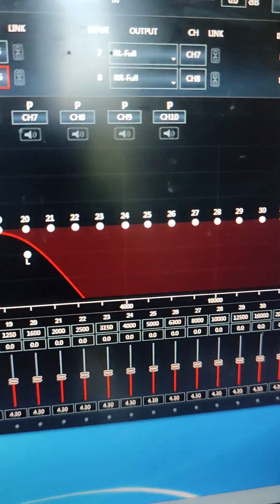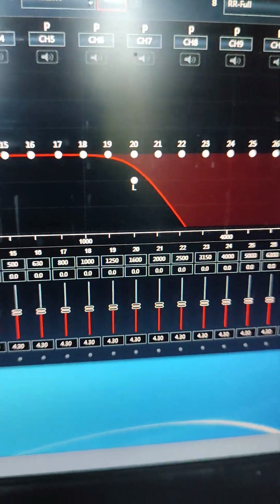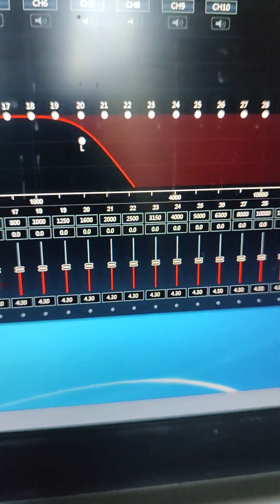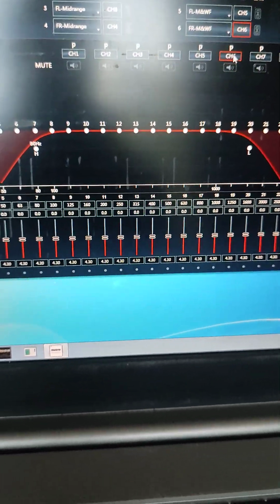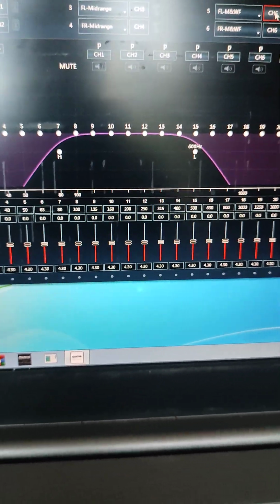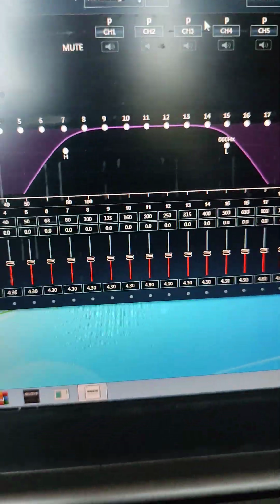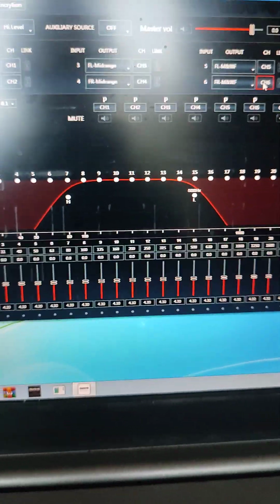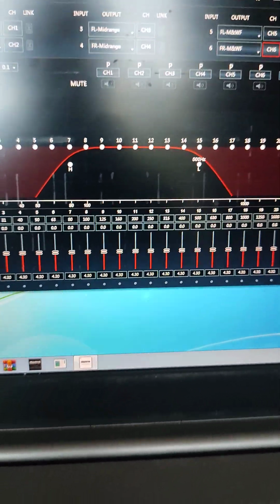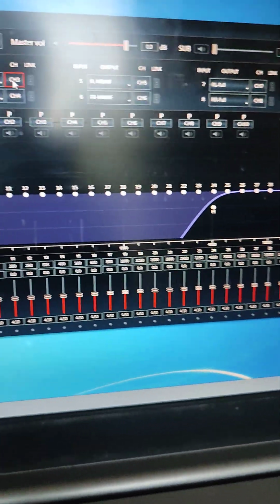You can research the frequency response of whichever speaker you're using, and at the moment we'll leave them at Butterworth filters, and that's fine. And then you'll see there that your Butterworth filter, those two channels 5 and 6, when you change them, their colors will actually show which ones they're playing. This one is 80 to 500, and this one should be the same. Let's check it, 80 to 500. So you'll see those two colors will help you choose, and as you test your frequencies, they should actually just change color and retain the frequencies to be the same.